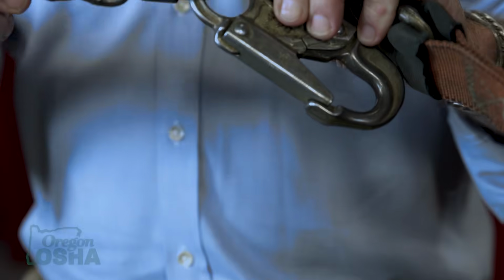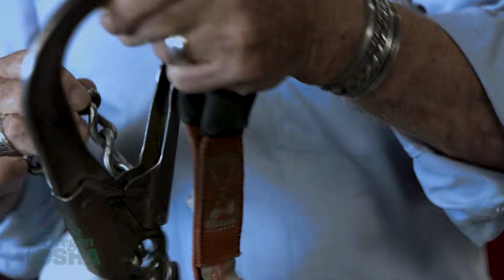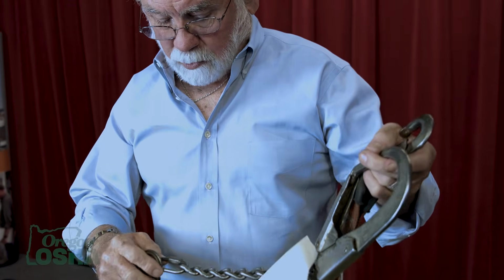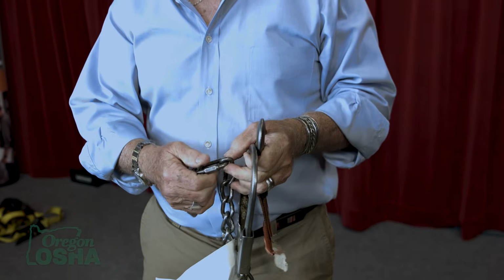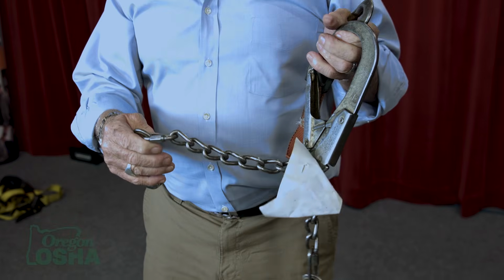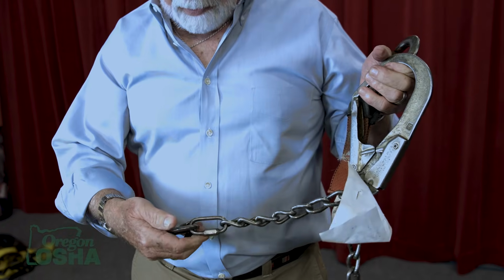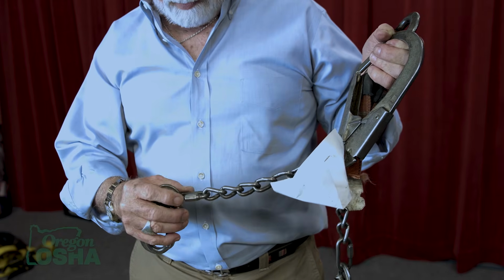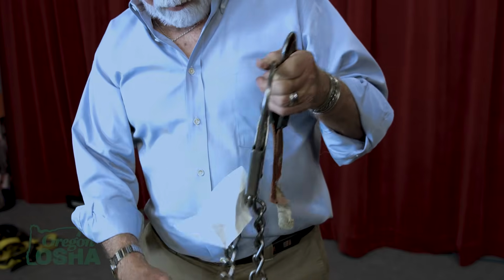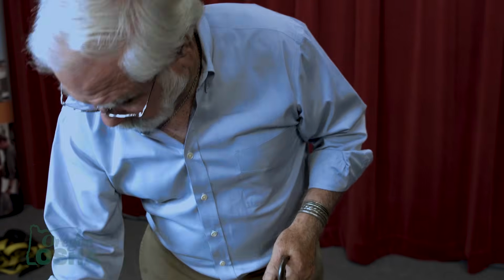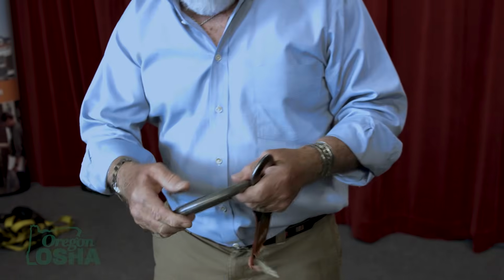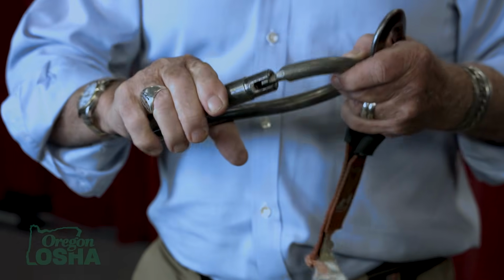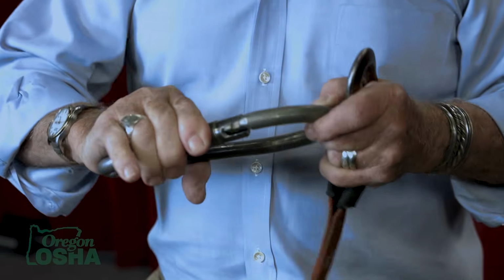It's interesting. Now here is a rebar hook on the other end, a legitimate chain from somewhere, and I want to ask the question, how do you think that connection right there is rated? Chances are it's not, but chances are it's convenient, and the person with the hook utilized older hooks, piece of roller chain, and something he bought at the hardware store. Please, if you engineer your own equipment, take out your own insurance policies. Bigger is not necessarily better. So here's an example of a large snap hook, opens and closes, but the spring itself is broken.